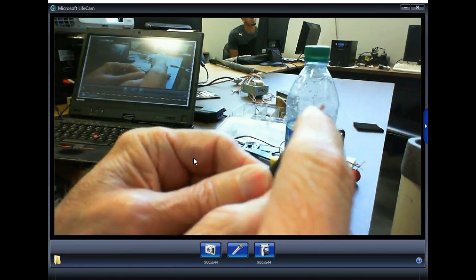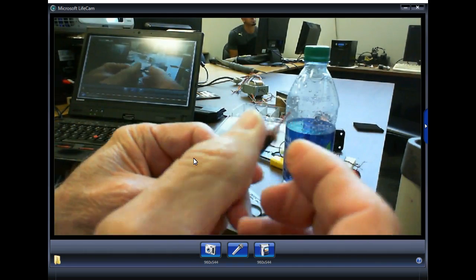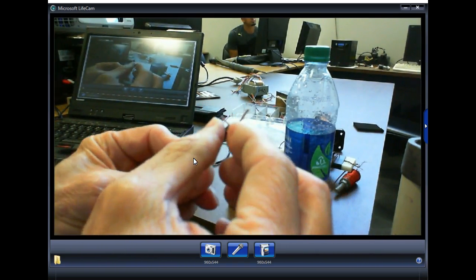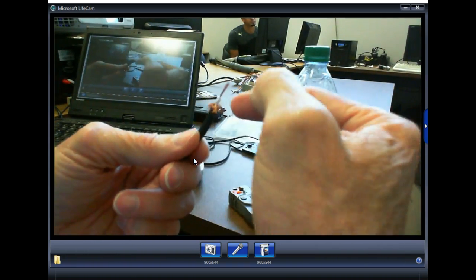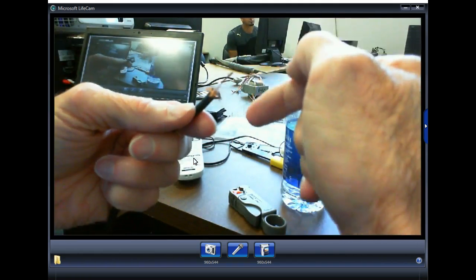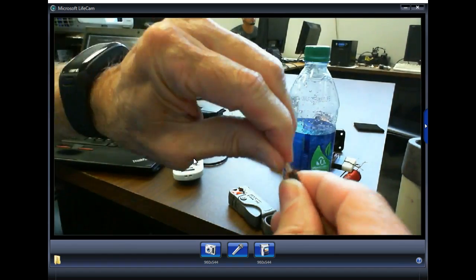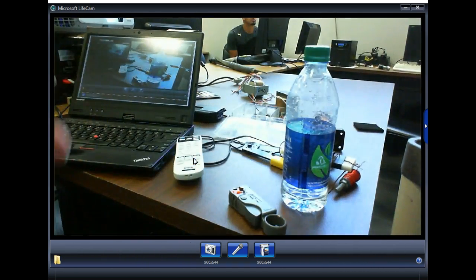This uses a copper shield, and different cables use different shields. RG6 uses an aluminum foil shield, and you'll see a lot of them. If you took the one your cable company had, it's going to use an aluminum foil shield, but then they have wire that wraps around it so you can make connection with the shield. This uses a stranded conductor. Looks like we need to adjust it a little bit, but anyways. And on the cable, you should see RG8/U coaxial cable.